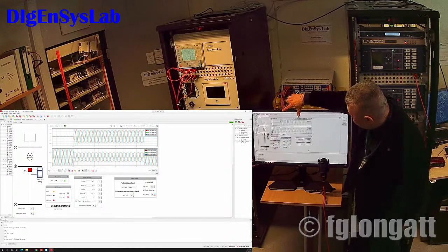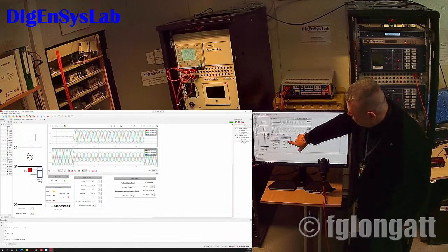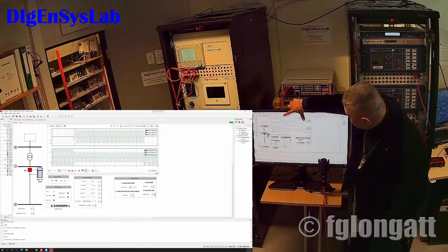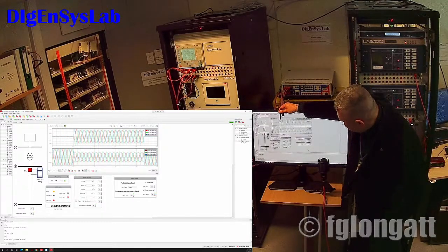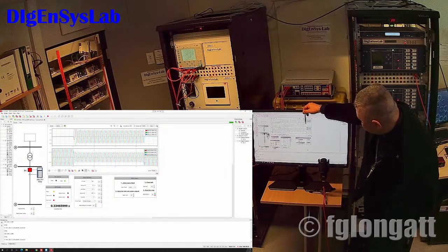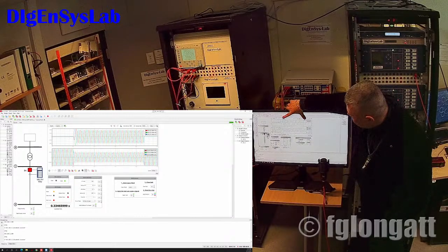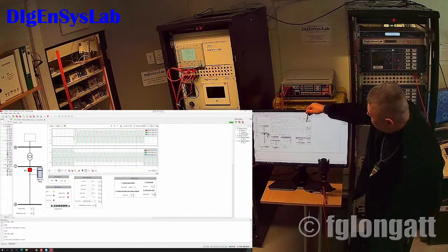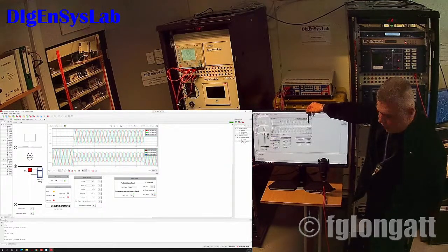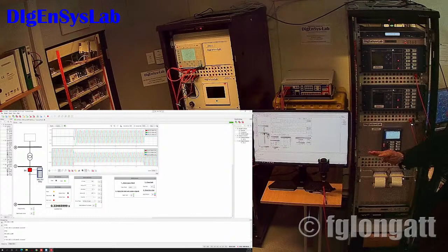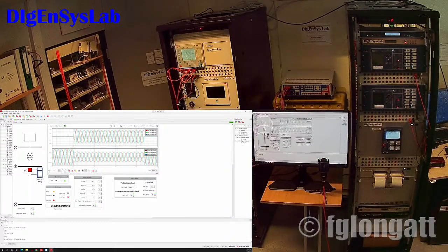And after this period that is related with this time delay, that is around, let's say this is 0.1 and this is around 0.4 something. Well, 0.0334 is the total time for clearing the fault, okay? And you can see after the clear, the current is going to 0. But people will say, no, that is a simulation because you can do that with PowerFactory. To be honest, you didn't do that. What you did was the real stuff.